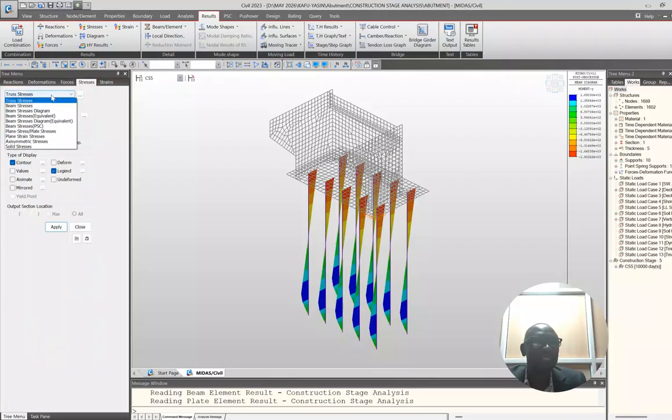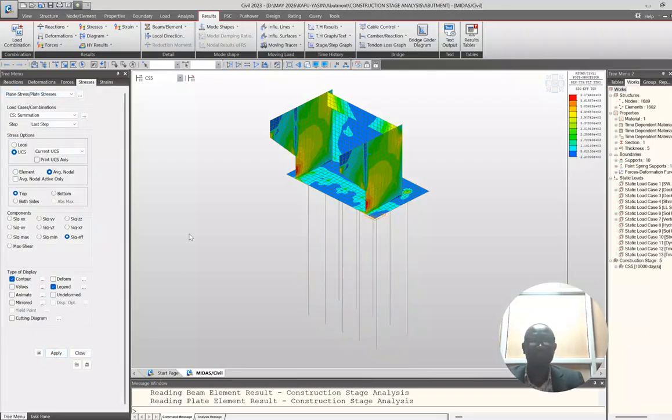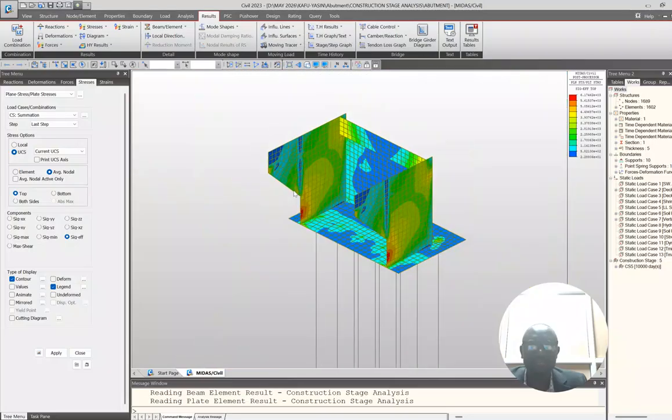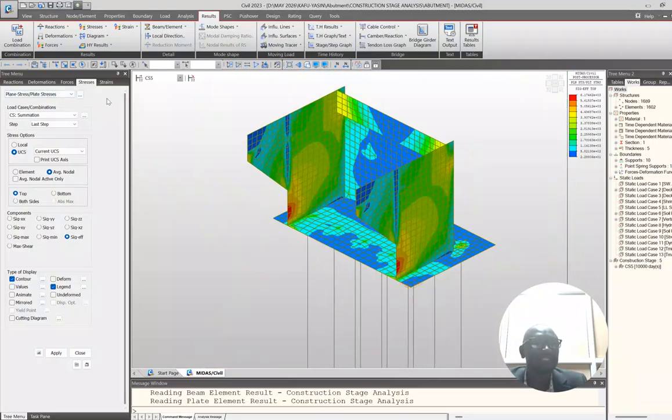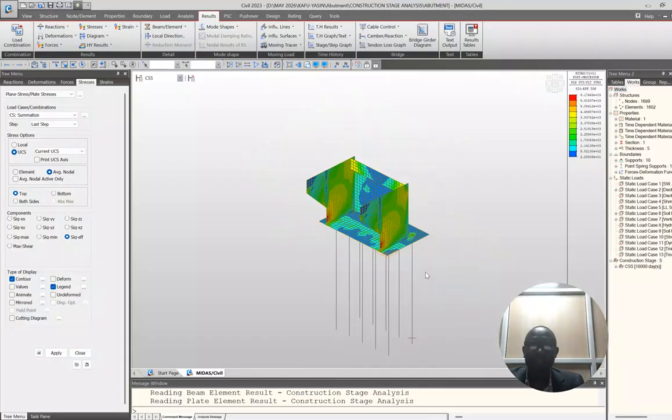The same would apply here. This is your stress generated considering the dead load, without applying the other loads like the deck loading, the soil pressure, hydrostatic, and the dynamic load from earthquake. This is basically self-weight, but shrinkage is there, and also creep. Shrinkage is an element of temperature effect and the rest of it. So you are able to see all that. These are the stresses built up. So it's very important that we consider construction staging.